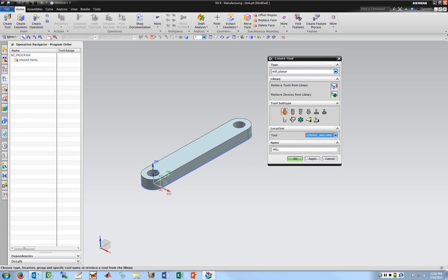You can see down here, by the way, this XM, YM, ZM. Those correspond to the X, Y, and Z coordinates for the mill. So this would be the X, which is generally left-right. This would be the YM, which, looking at the machine, would be into and out of the machine, and then Z is the up and down axis of the machine, which is pretty standard for a 3-axis mill. That lines up originally with the axis of our part. If I want to change that, I can either change the rotation of the part, or I can change the machine's coordinate system, which I'll do in a later tutorial. For now, just bring your part in with your X, Y, and Z aligned how you'd align it in the mill, and you'll be okay.